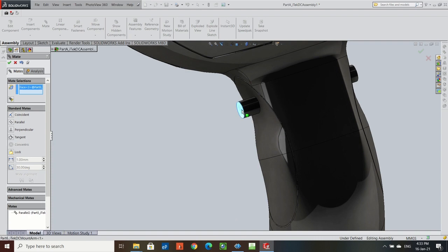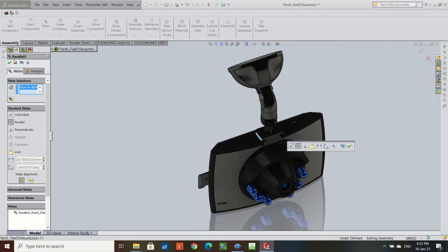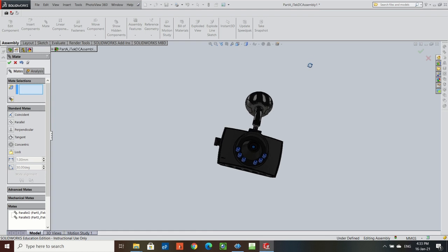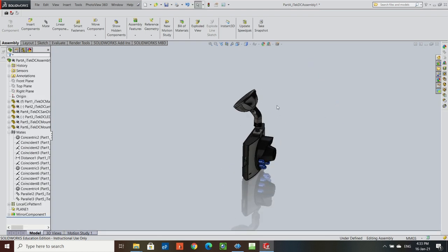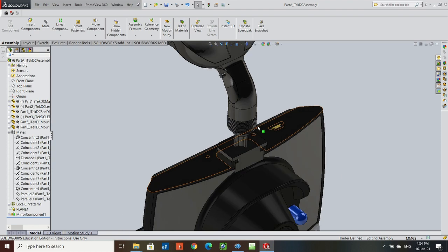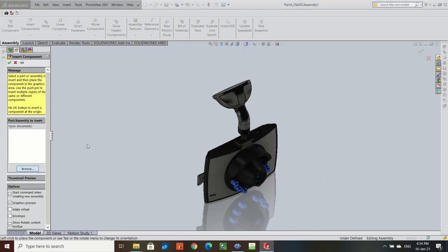I'm now going to click on the side here, of the mounting block, and I'm going to add again another parallel relationship there. So now that is completely fixed in that position, and the value of that is that when we go to do our drawn sheet, it's going to allow us to produce drawings that are neat and consistent across all the elevation plans and end views.